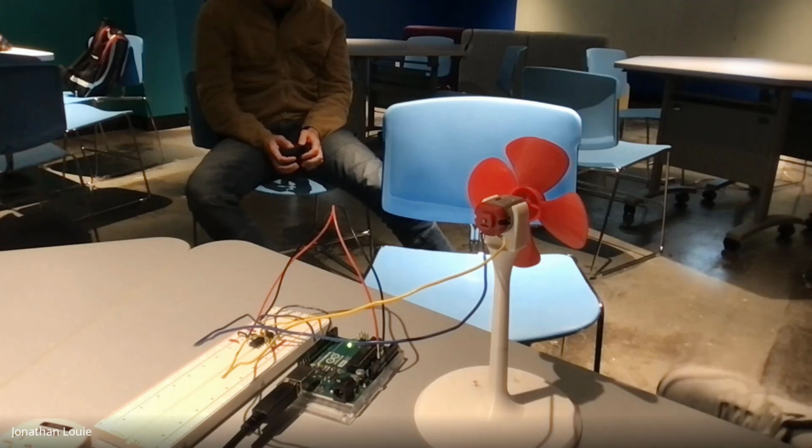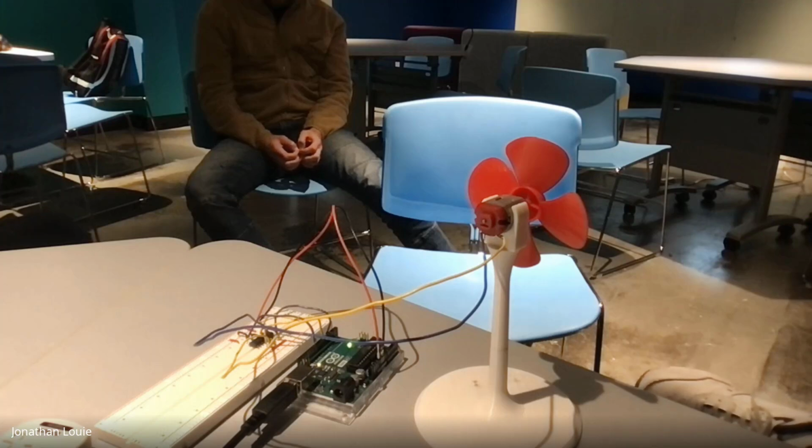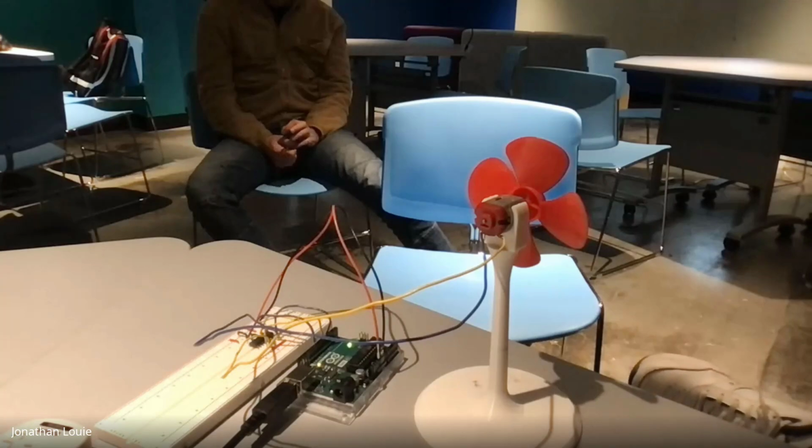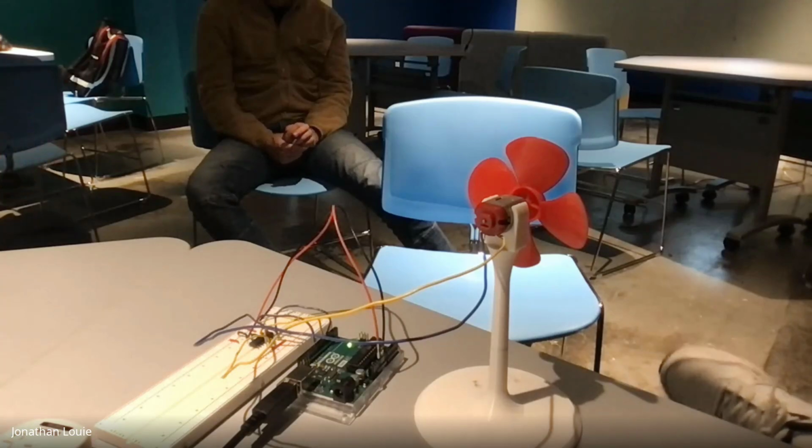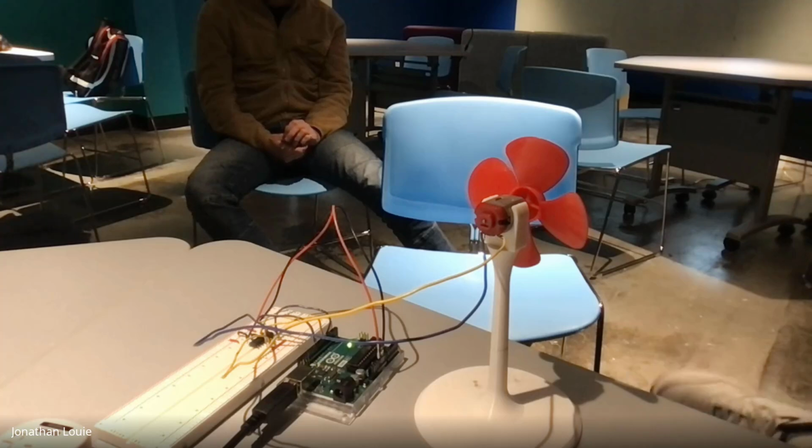So the fewer steps you have in that, the easier it is. And if it's on a board, there's things called pick and place machines. So machines can basically do all of these components by themselves without human interaction. So the more you put on the board, probably the cheaper it's going to be, with fewer mistakes, etc. You can automate the testing and construction, and the overall product might be a little bit cheaper that way. But of course, you lose the flexibility.